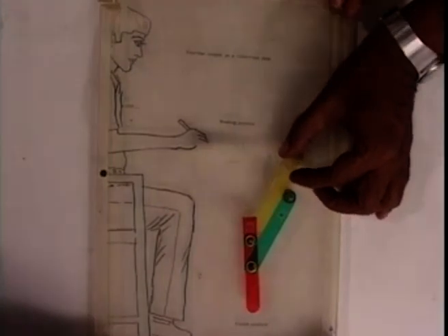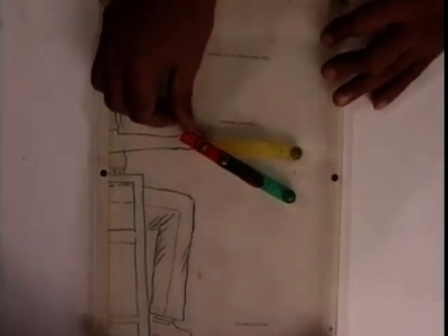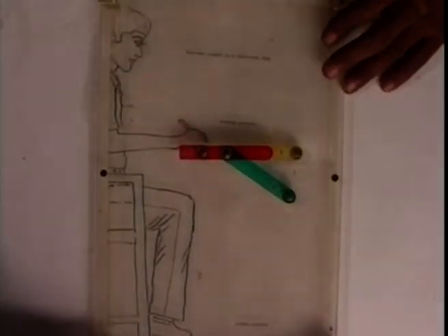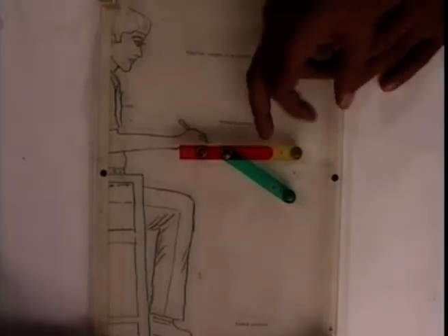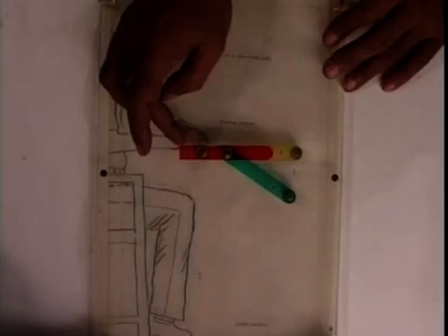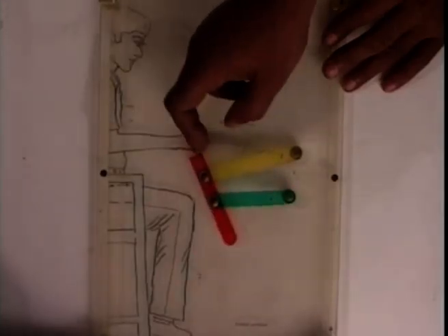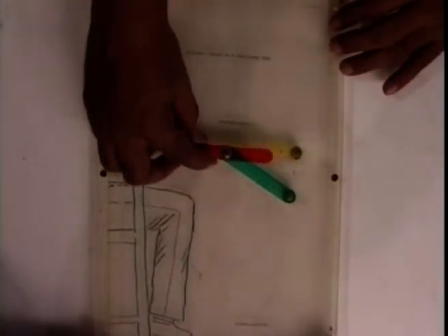So, this is a motion guidance problem, in that I want the coupler of this 4-bar linkage to move from this configuration to this configuration in a prescribed manner. There is no need to coordinate this movement because our objective is to have it locked at the writing position, and we can take it away to the folded position. So, this is the example of a guidance problem or a motion generation problem without any coordination with the input movement. Next, we see the model of another 4-bar linkage which is used as a tipper dumper.